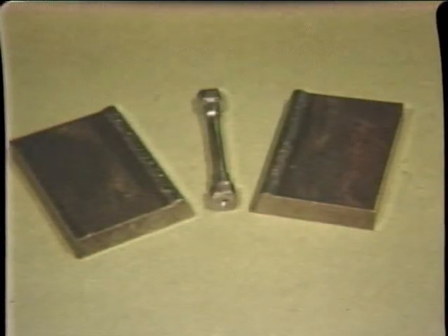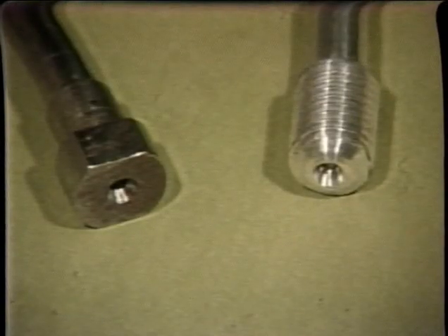All weld metal specimens are machined from the center portion of a test coupon. It must consist entirely of weld metal in the reduced section in order to ensure evaluation of weld metal only. The ends of the specimen are shaped to fit the jaws of the testing equipment being used.